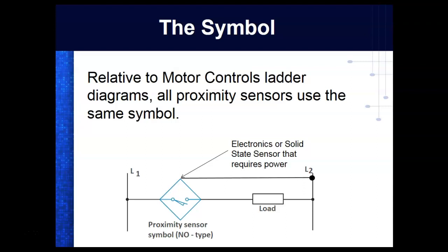If it's a high voltage sensor, it might be a 2-wire sensor, which means it powers up through the load, so the sensor fails. It drops about 4 volts, but that's still leaving 160 volts across the load. But if I'm running a low load sensor, like on a 24 volt supply, then odds are we're going to have to power that sensor up.